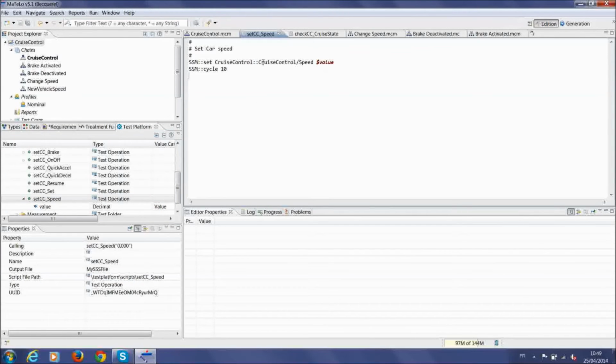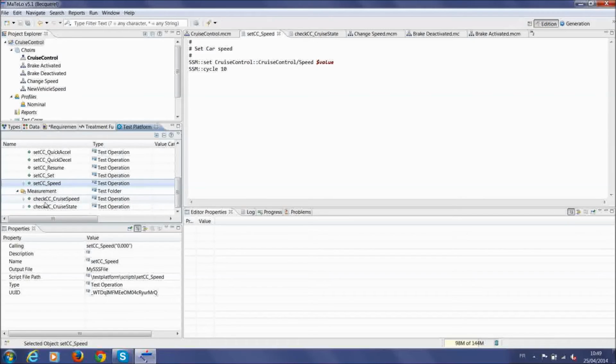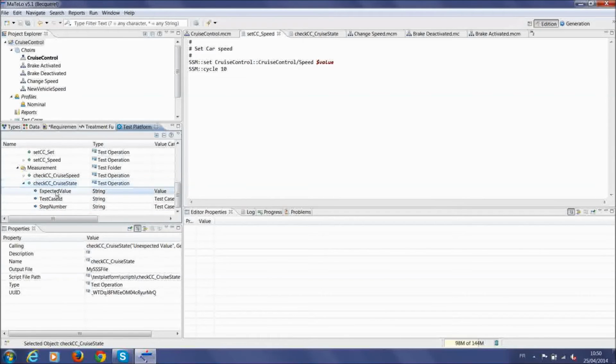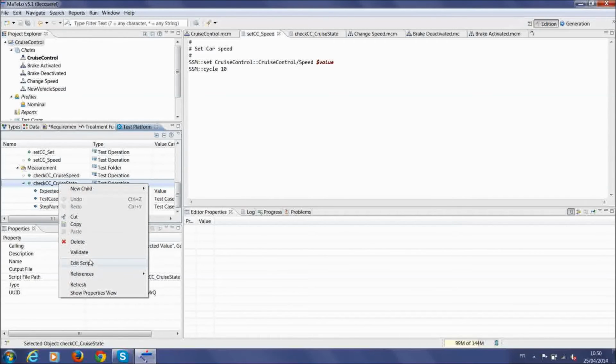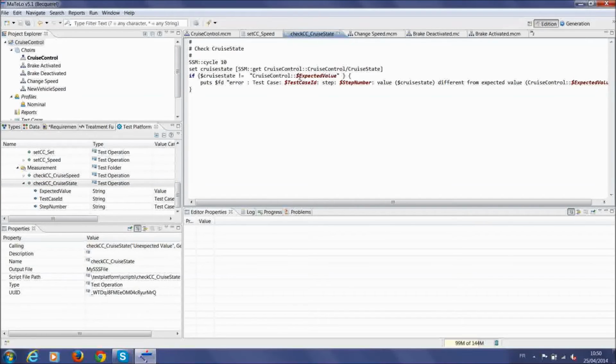To create the test cases from the model, select the generation window with the help of the button on the top left. Select the default strategy or create your own strategy. Select the substates of the model you want to parse or include in the generation. Select the appropriate algorithm to fit your test strategy. Click on the Generate button. The test cases appear in the main window of the generation perspective.